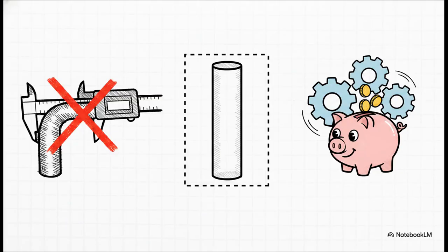So, let's wrap this up. What is the bottom line here? First, size alone does not guarantee your parts will actually assemble. A part can measure perfectly but still fail if it's bent. Second, ASME rule number 1 bridges this exact gap by mandating perfect form at maximum material condition. Third, combining size and geometric tolerance creates a virtual condition, a strict envelope boundary that your part absolutely cannot violate. And finally, applying these rules clearly and correctly drastically reduces scrap, lowers your costs, and keeps your production running smoothly. Rule number 1 really is your ultimate safeguard for functional assemblies.